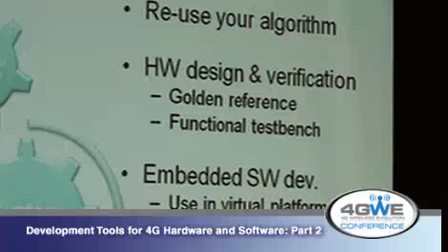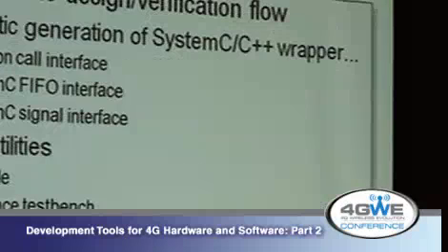Use that as a golden reference for your hardware development, then take it over and use it as a reference for the embedded software developer, so that the embedded software developer can start prior to the actual chip being available, which will greatly de-risk your flow, because you're building up top-down from the development of the algorithm.